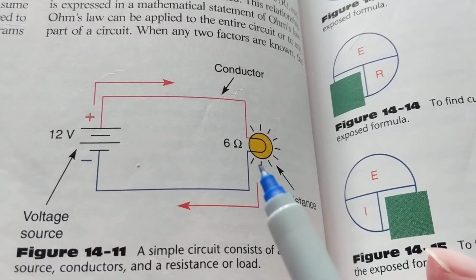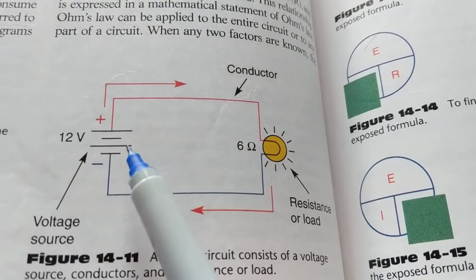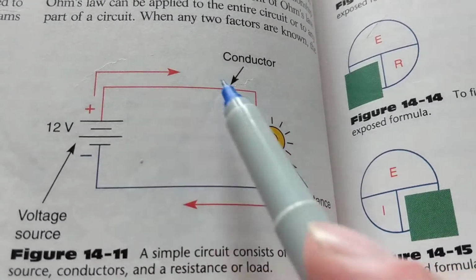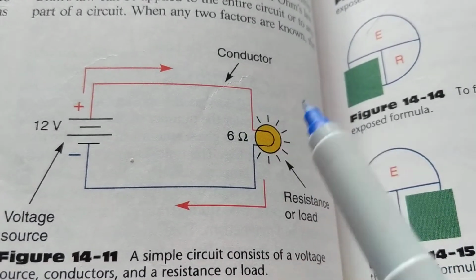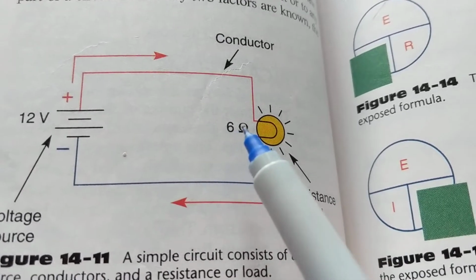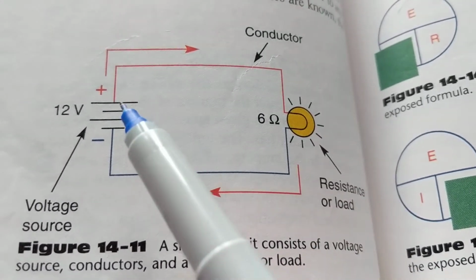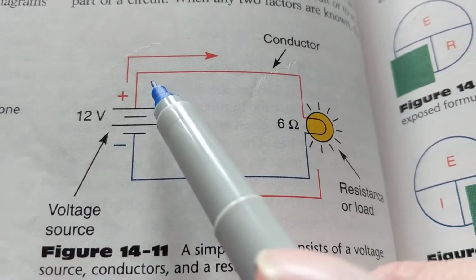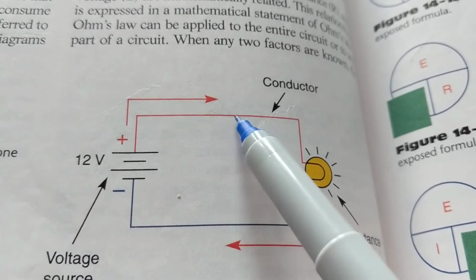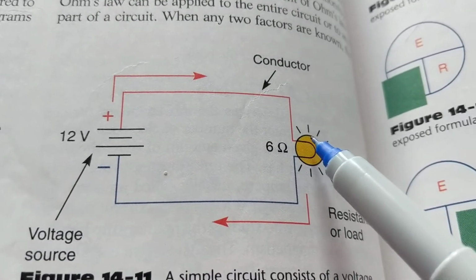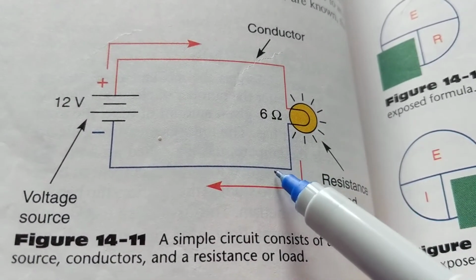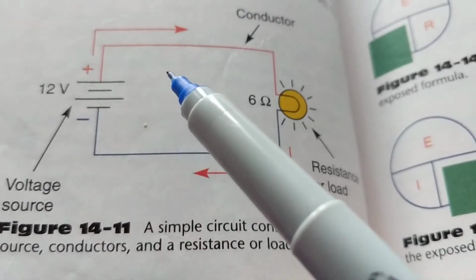The basic circuit. We're dealing with one bulb over here. We have a power supply over here, our famous automotive battery. And the positive is connected here, conducted through wires. This filament, this bulb, has some resistance in it. In this example, 6 ohms. Current flows from the positive through the conductor, through one side of the filament of the bulb, comes out the other side and back to the battery.